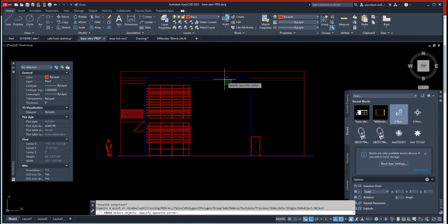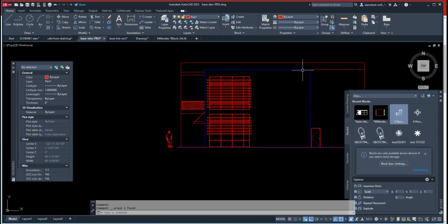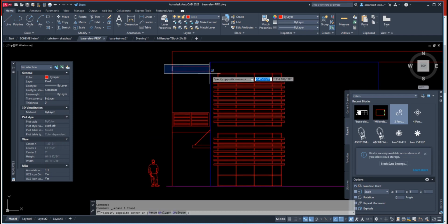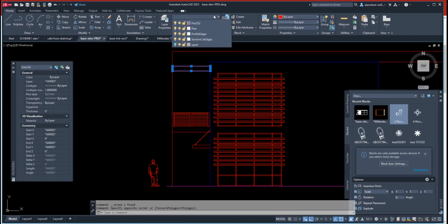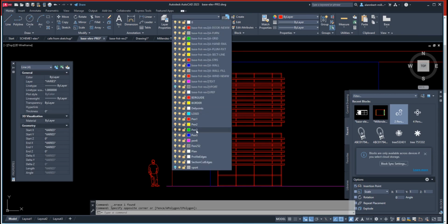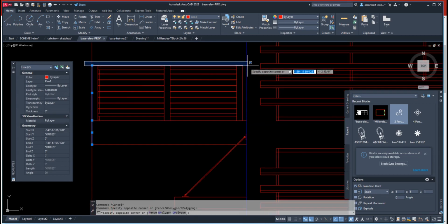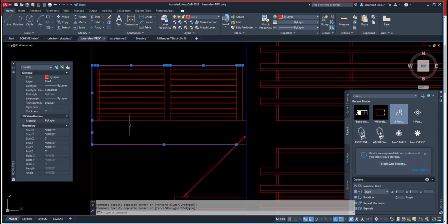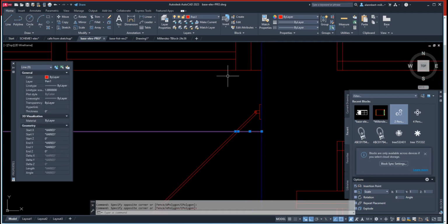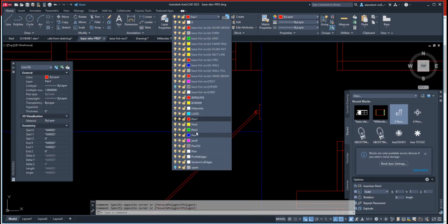Just like we did on the other elevation, fix that. There is no line here also. And this one is the one that is to be the strongest line because it's the one up front. This one is further back. Okay, so this one, we're going to change that to a layer pen 3, I guess, yeah. And this one too, this whole piece here, the top piece, and this one, including this, supposed to be pen 4 or pen 3.